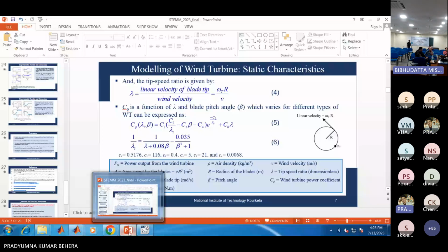No, sir. Actually, the PI block input is voltage and the PI block output is current. How are you converting voltage to current? That is my question. See, if you do the state space modeling of a boost converter or buck converter and find the transfer function, you will get various transfer functions: output voltage with respect to duty, inductor current with respect to duty.